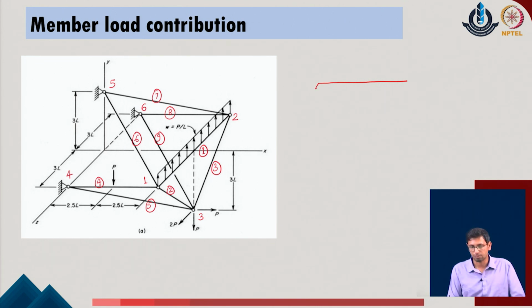This is the member which is kinematically restrained first, because, as we remember, to evaluate the reactions in the given system, the truss problems up to now which we did did not have member loads, but maybe the space truss case we have taken in which member loads are also active. So, before going through this part, we must also accept that it is not always the case that trusses will not have loads active on the member span. In a real structure, the loads could be active on the member span also. The only thing is, while doing the analysis, we convert all these loads into equivalent joint loads of the given problem.